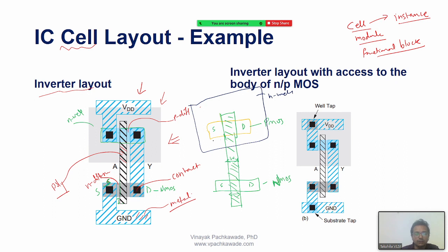So you see it in this gray. That's all. Now I want the metal layers. With metal, I am forming the circuit of a CMOS inverter. I know that here I need contacts. So I will first draw the metal, and that's my VDD. Then I know that the source and drain of the NMOS and PMOS are connected. That forms the output Y. The gates are already connected; I can draw the metal here also, but I will simply say it's the input A. But with metal also, no problem, I can draw the metal. And then I see now this is covered, the source, and then I have this ground here.